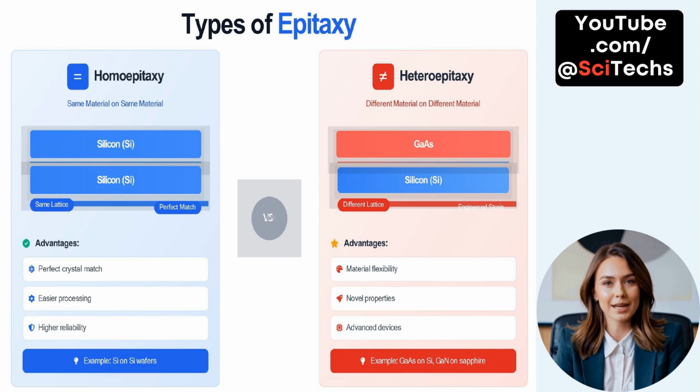On the other hand, heteroepitaxy uses a different material for the epitaxial layer than the substrate, for instance, gallium arsenide, GaAs, on silicon. This introduces lattice mismatches, which can be leveraged to engineer strain and create novel properties. Heteroepitaxy offers greater material flexibility, enabling the development of advanced devices with specialized electronic or optical characteristics. Examples include GaAs on silicon or GaN on sapphire, which are used in high-speed electronics and LEDs.